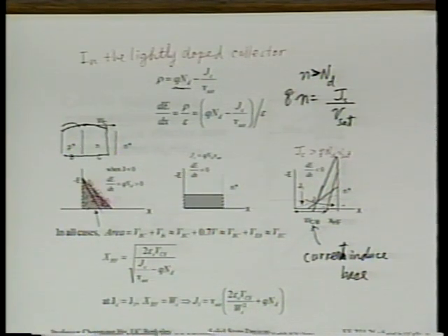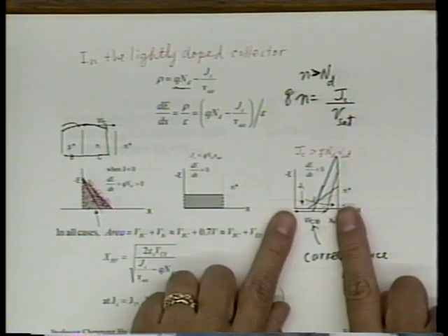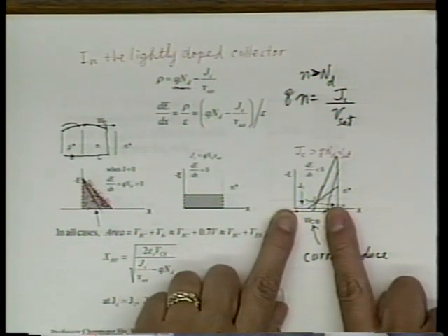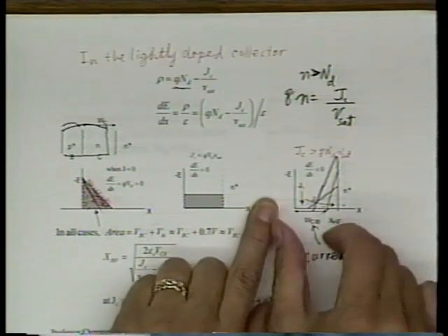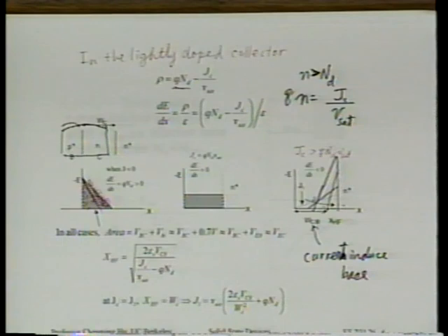As current increases, the base gets wide. Now we all know the speed is proportional to the base width squared, right? Number one, it's very sensitive to base width. And number two, the potential size of this current-induced base is many times larger than the actual base, because the lightly doped collector is much thicker than the real base.